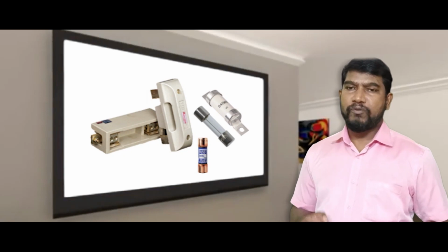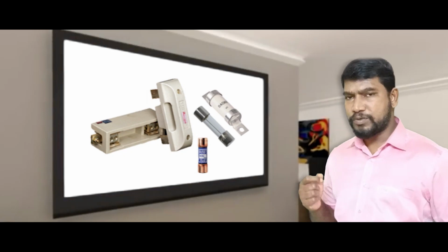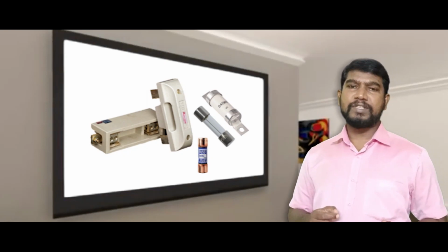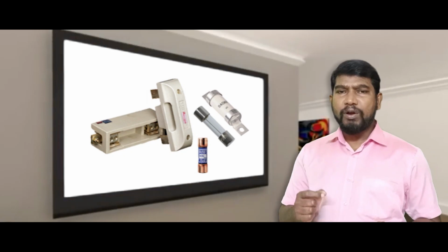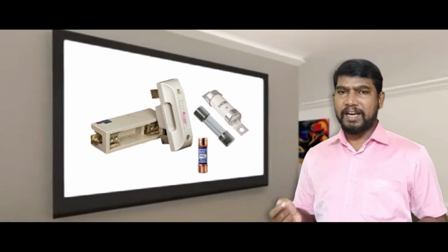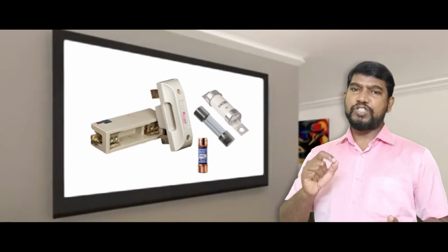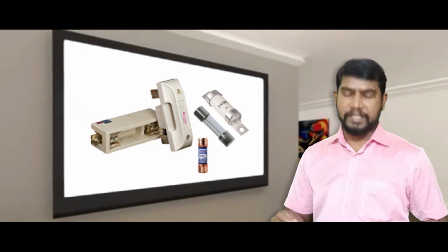Usually, an alloy of tin and lead is used as a safety fuse. A thin wire of the alloy of tin and lead is used. It has a comparatively low melting point, because when excess current comes, the fuse wire gets heated, and because of the small heat generated there, the fuse wire gets fused or melted.